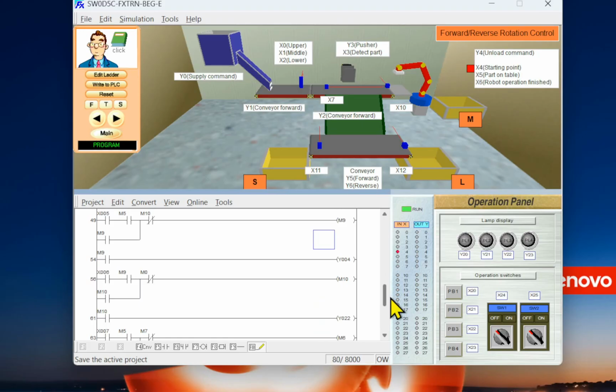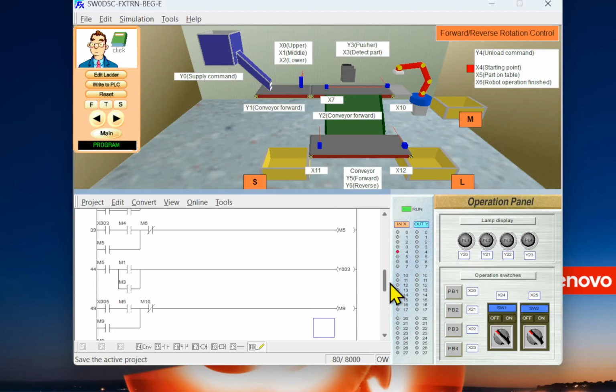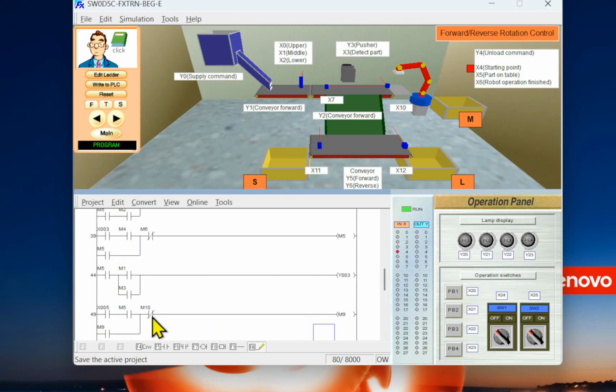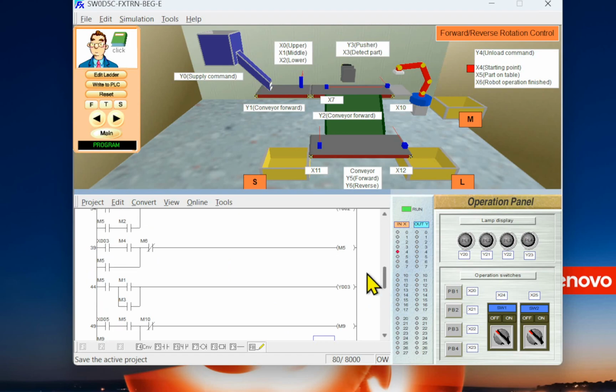The medium size I use M9, right? M9. Yeah. Okay, in this one X3 over here detects the object side. If the last side, the pusher is working, it must be working, right? And for this small size Y3 must be working too. And X3 indicated it's medium size. The conveyor keeps going, carrying the object to the other end of the conveyor, right?